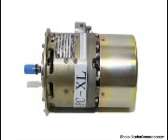At the instant that each brush is contacting two segments on the commutator, positions A, C, and E in Figure 9.7, a direct short circuit is produced. If an EMF were generated in the loop at this time, a high current would flow in the circuit, causing an arc and thus damaging the commutator. For this reason, the brushes must be placed in the exact position where the short will occur when the generated EMF is zero. This position is called the neutral plane.